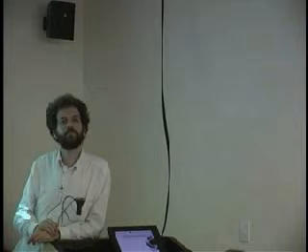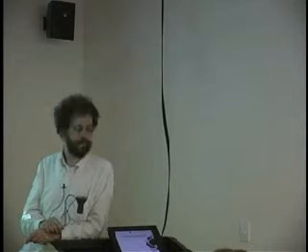Yeah? What controls the... Whatever you'd like. So E is an input to this thing that we're going to turn on and off before the clock goes from low to high. And so some of the time E will be high, in which case we say, go ahead and take the picture. And some of the time E will be low.